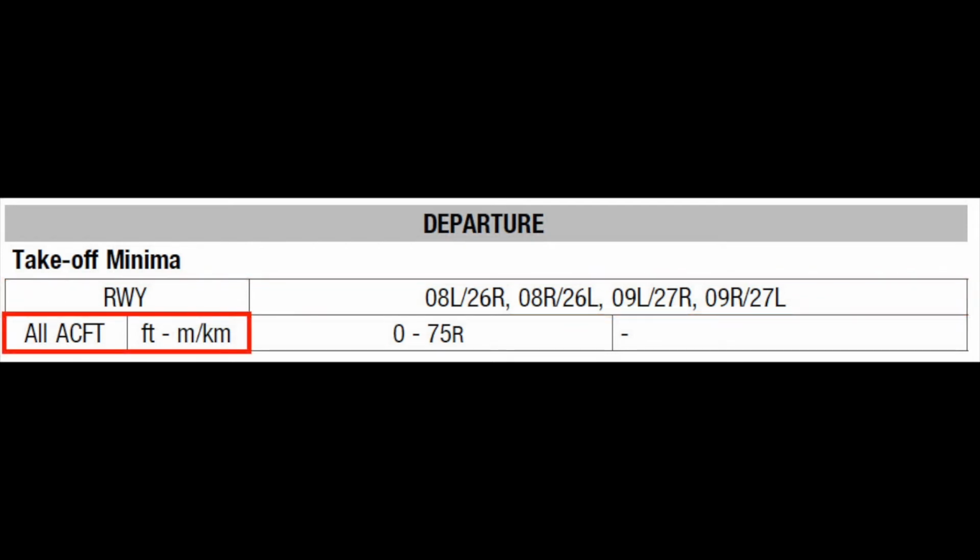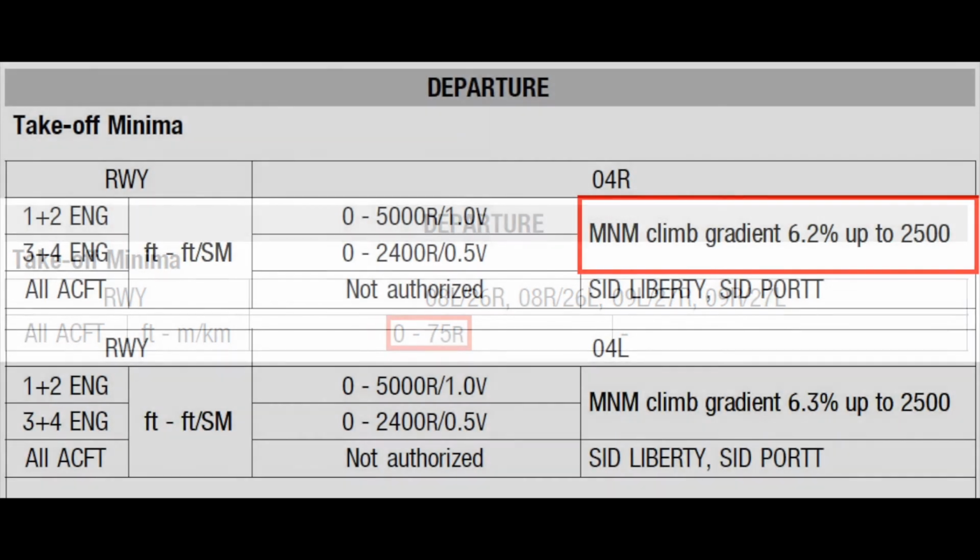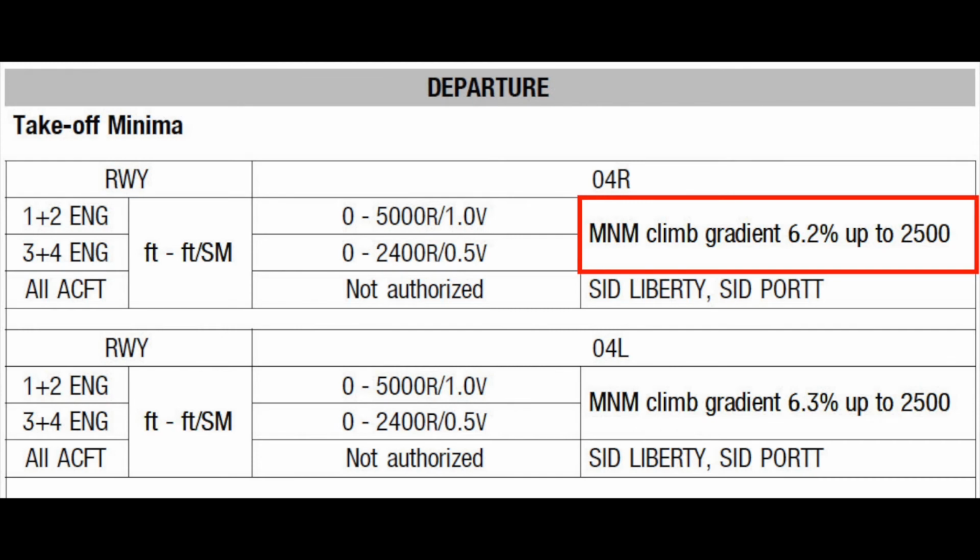Aircraft categories will be displayed alongside the minimum value units. Minima are shown with a ceiling value first, with RVR and/or visibility after. Climb gradients, when published by the state and when it exceeds 3.3%, will also be shown. Please note that ATC climb gradients will not be displayed.